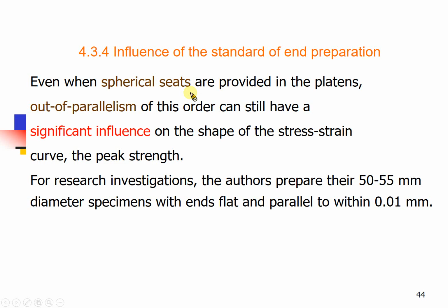To avoid eccentric loading, we use a design called the spherical seat. Even if you use this, if the end of the specimen is not really parallel, or not really perpendicular to the axis of the sample, then you still have a significant influence on your stress-strain curve and on the strength. So it will be quite sensitive.